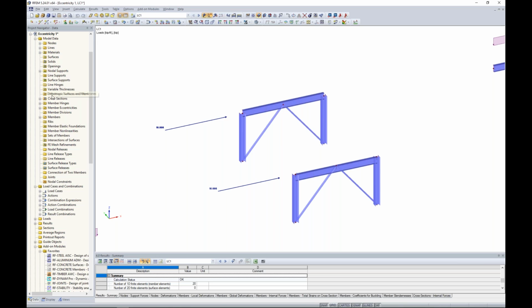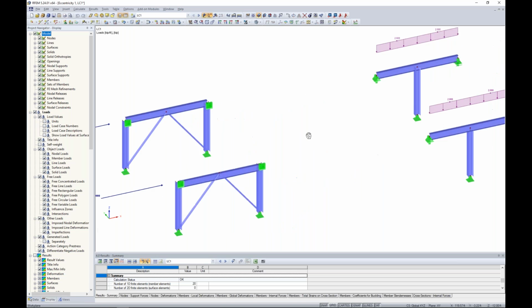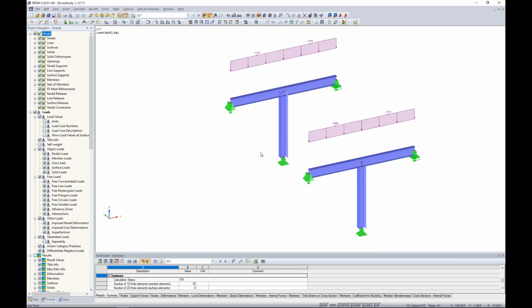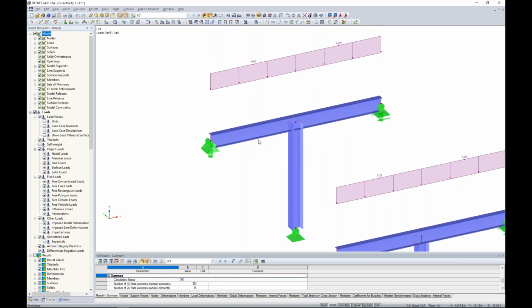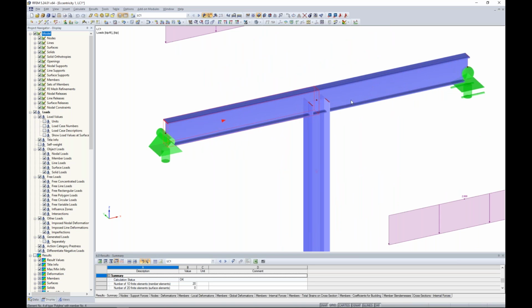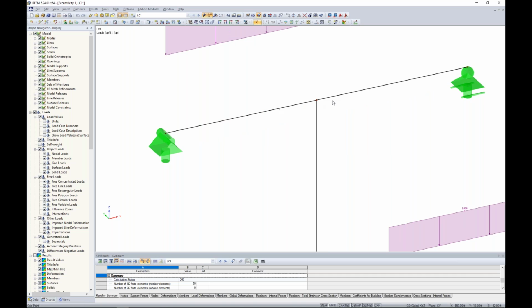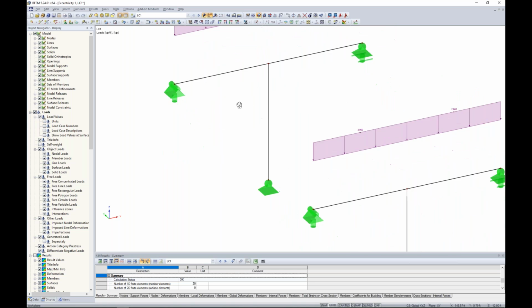So we'll cancel our visibility mode. Let me once again turn on my nodal supports. We'll move over to the right here. Just a T-type frame. And with this system here, let's assume that we have these beams framing over the top of this column. And once again, my first example in wireframe view, everything's framing in at the center line here. So just default settings, no eccentricities.